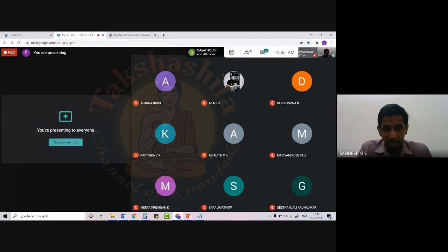One more thing you have to take care of is that in this case, you have obtained a value of 134, right? You cannot round it up to 140, because then the spacing between the stirrups is actually increasing. In that case, the minimum requirement may not be satisfied, because in this particular critical section, you require a spacing of 134.